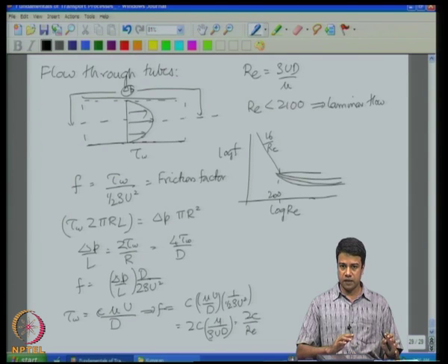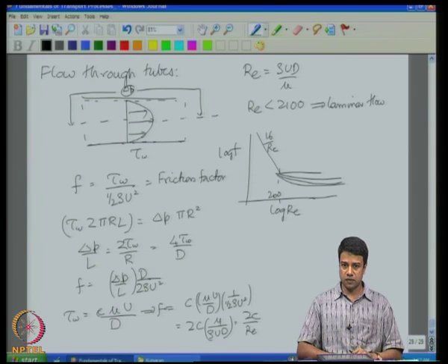And we can define non-dimensional fluxes by using the diffusion coefficient to non-dimensionalize the flux. That gives me the Nusselt number and the Sherwood number. These have to be a function of other dimensionless groups, and those dimensionless groups have interpretations. They are mostly either the ratio of convection and diffusion, such as the Reynolds number and Peclet number, or the ratio of two different diffusivities.